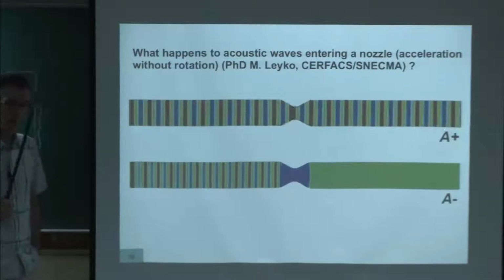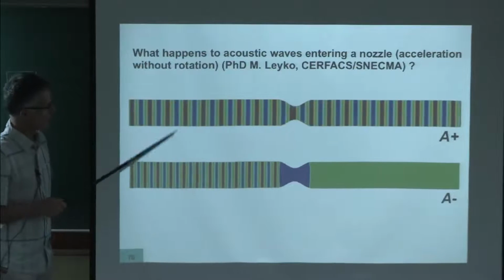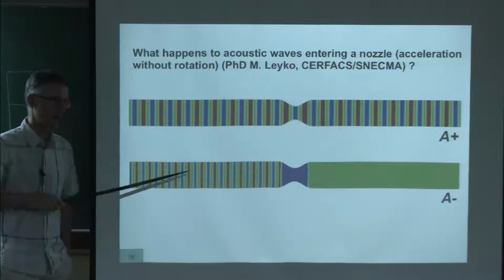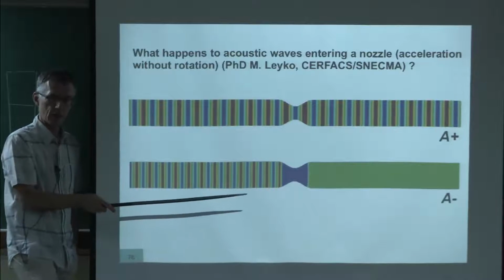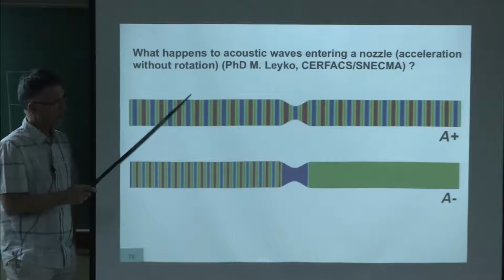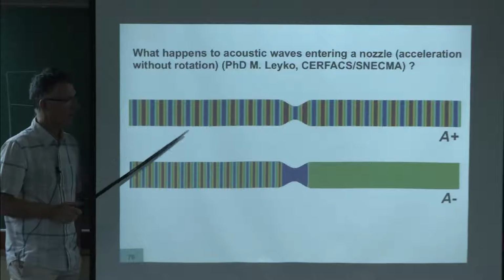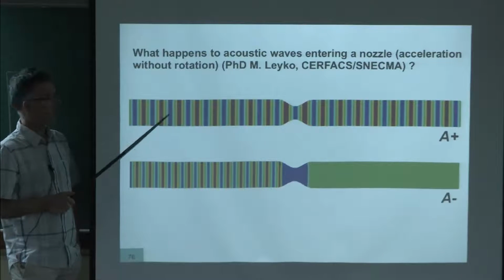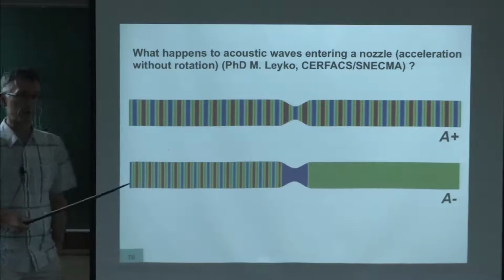So we care about combustion instabilities. That's what we want to know. If we do the ratio of this thing to that thing, we have the reflection coefficient of the nozzle. Okay? So we can construct the acoustic reflection coefficient of a nozzle. It's the ratio of how much comes back to how much is going in. This depends on the wavelengths, so it's a function of frequency.